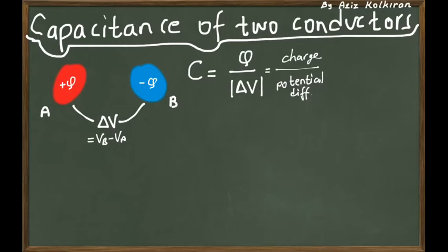It is similar to the definition of the capacitance of a single metal object, again Q divided by the voltage. But this time the potential difference is the potential difference between two pieces of the conductor. This conductor may have some absolute potential, and that conductor some other absolute potential, but we don't care about their absolute potential, we care about their potential difference.